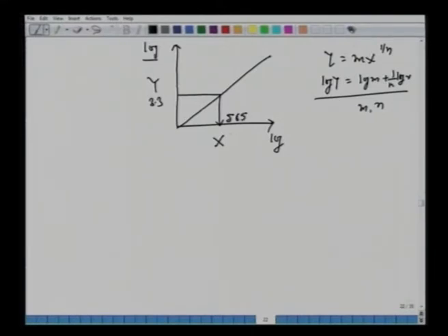Once we know the values of y1 as 3.3 and 565 as x1, you can make a balance, which we did earlier. For stage 1, S1 will be equal to LS, which is 1000, times 9.6 minus 3.3, divided by the solid phase concentration, which has increased from 0 to 565.